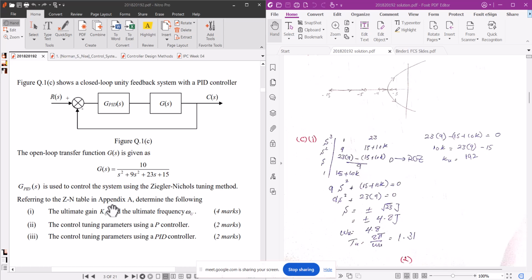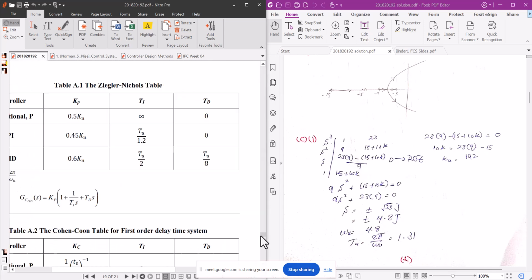And if we measure the time period of this oscillatory system and determine the frequency, which is f equal to 1 over T, we get the angular frequency by 2 pi f or 2 pi over T. So this will be the ultimate gain, and its table is shown.